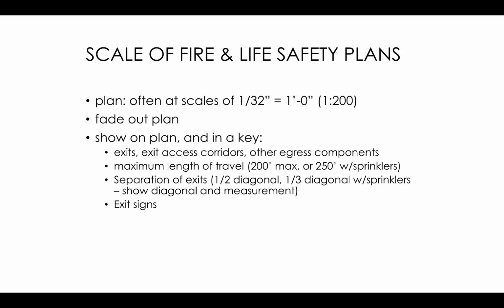So what I typically do is I just sketch in where the exit signs are too, using a diagrammatic indicator. That helps me think about, am I having ceilings? Where am I going to put that exit sign so that a door doesn't swing into it, because the ceiling is too low, but it's still visible?